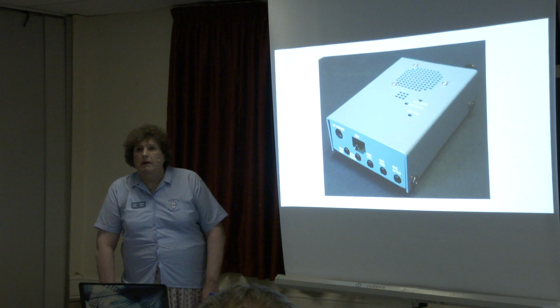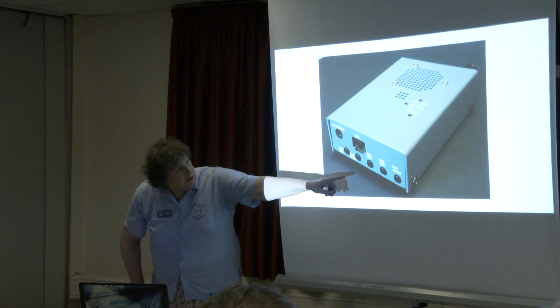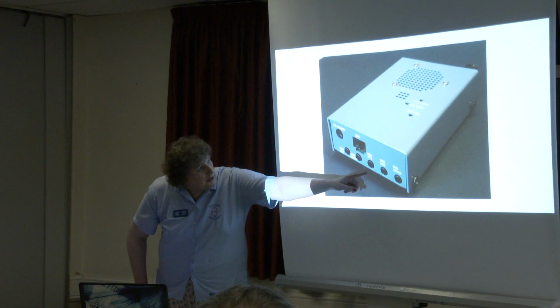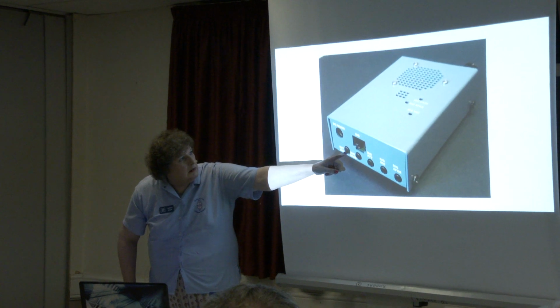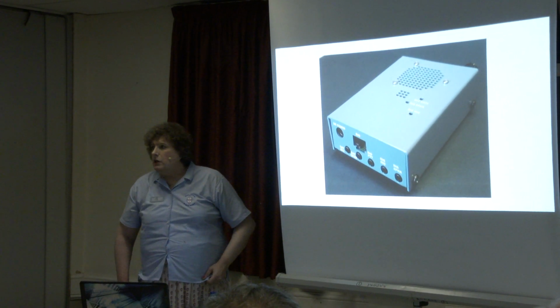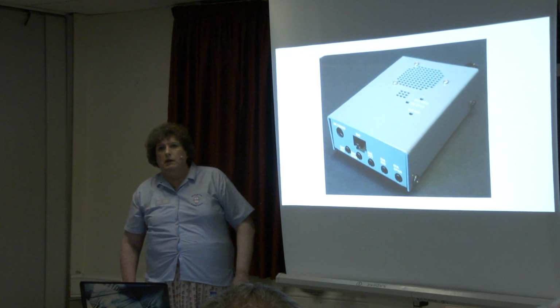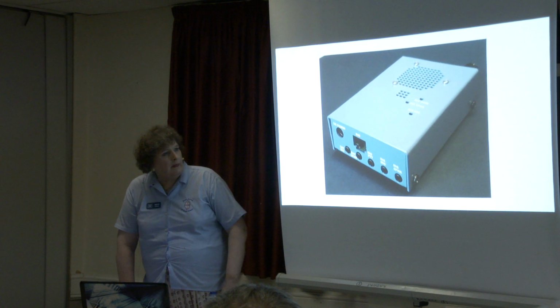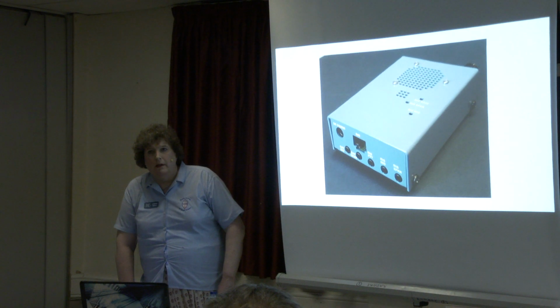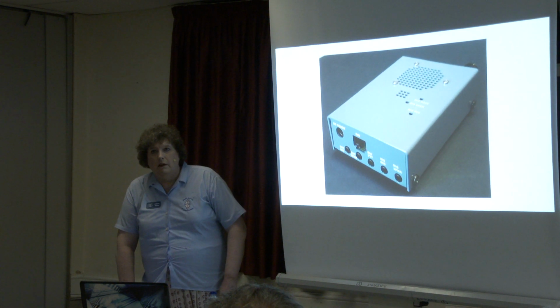How do you plug that into your radio? You have the sockets here. These are 3.5mm sockets, which are used for audio in and microphone, etc. So you would make up a lead that couples that to your microphone socket on the front panel, which hopefully has got an audio out as well.